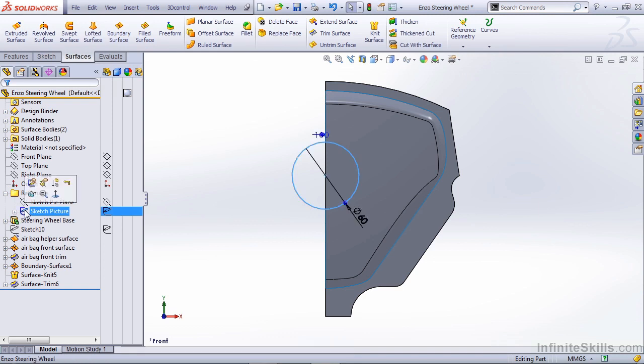If this sketch was used in an original feature, that would have a different implication because it would have an original parent-child relationship farther up the tree, and reorganizing it wouldn't allow that relation to rebuild. But in our case, the sketch picture holds no relation to anything else in our current part, so it's important to leave those relationships intact.